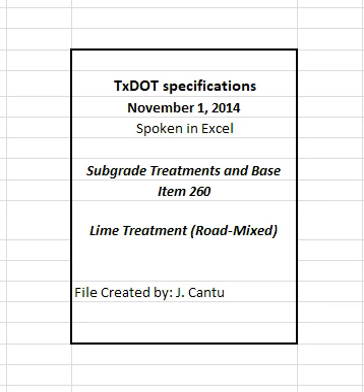Reworking includes loosening, adding material or removing unacceptable material if necessary, mixing as directed, compacting, and finishing. When density control is specified, determine a new maximum density of the reworked material in accordance with TEX 121E, and compact to at least 95% of this density.